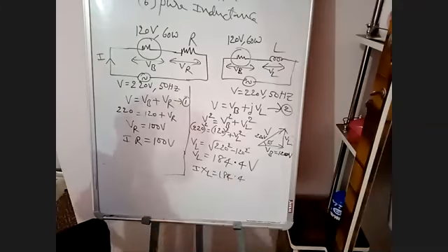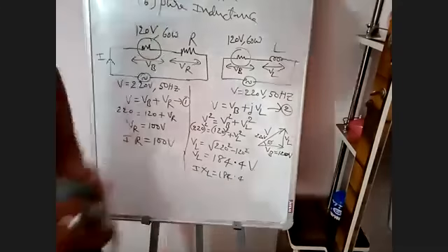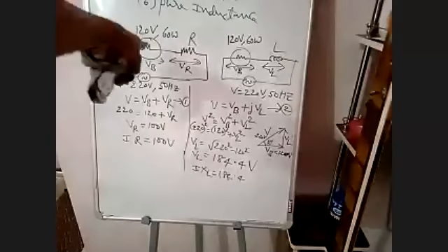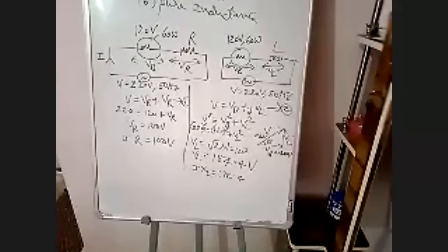In series, current will be same. Whatever the current flowing in the bulb, the same current will flow in resistance also. Similarly, in the second case, whatever the current flowing in the bulb, same current will flow in inductance also. Therefore, I is same in bulb and resistance. How will we calculate I value? If I know the I value, I can get R and XL.